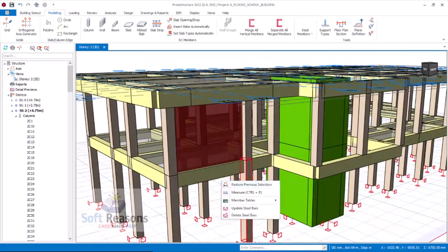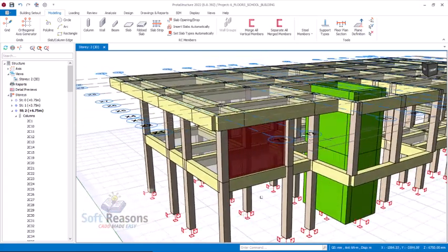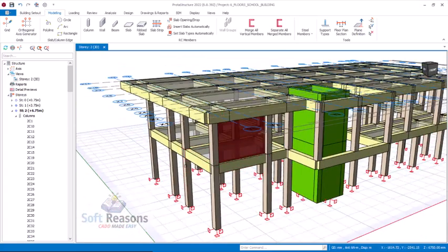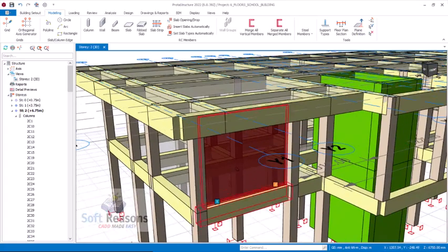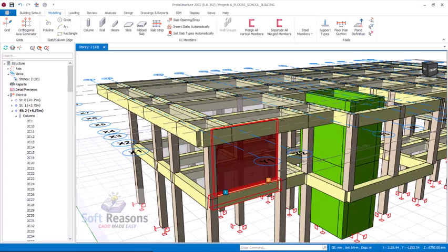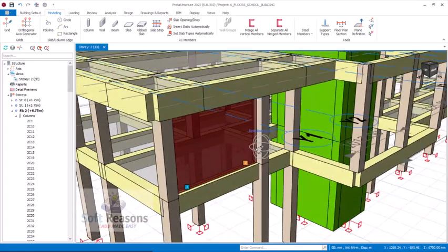You should also know that there are some walls that have windows placed on them. Having been designed for the worst condition, most of the time you may decide to just overlook those walls and have them closed up without opening the windows.